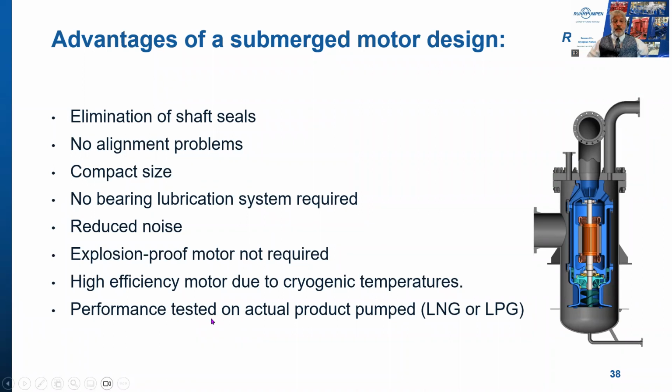The pumps are tested on the actual product pumped, LNG or LPG most usually. Most pumps, of course, are tested on water. Because this is an electro-submersible pump and this motor is wet, the fluid passes through the motor, you can't use water, can you? And therefore, it's essential that we test it on LNG or LPG.